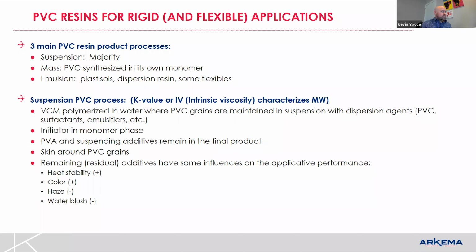And even changing seasons. We know that when we're going between summer and winter, things that have to be put into the resin to keep anti-stat properties in check can change. That can influence your processing if you're making windows or foam or something like that, how it's stored in your silos. All of that can come into play and be kind of subtle.